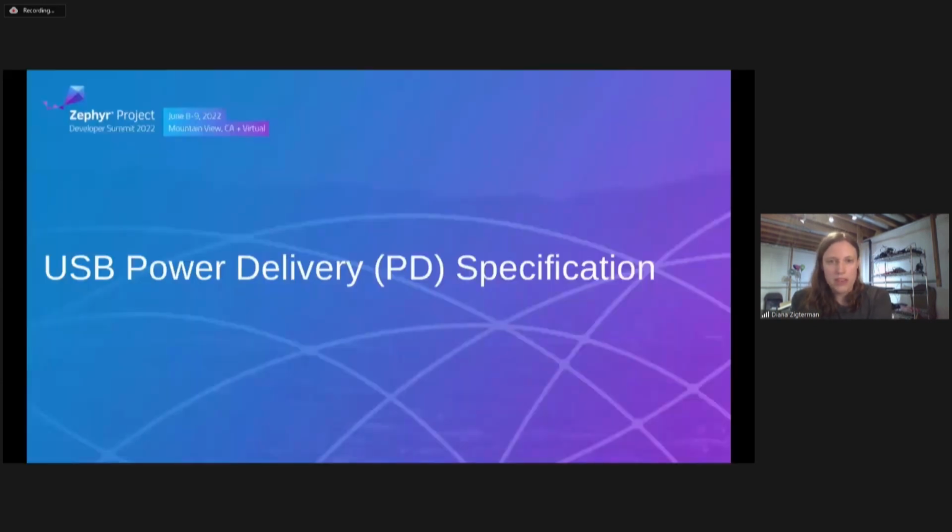But if you have power delivery, we can delve into the power delivery specification. This is a separate specification from Type-C, also available on USB.org. And everything in this specification is what happens after the Type-C layer has gotten to that Attached.SRC or Attached.SNK state.